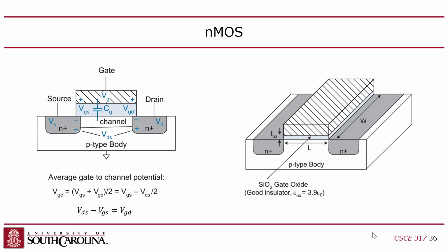Okay, so as I mentioned, generally you want this length to be as short as possible. This length is what you hear about when you hear a 7 nanometer process or a 4 nanometer process. It used to be that a 45 nanometer or 28 nanometer process referred to this length, the minimum feature size. Nowadays, when they say Intel is down to 4 nanometer, that's an equivalent.